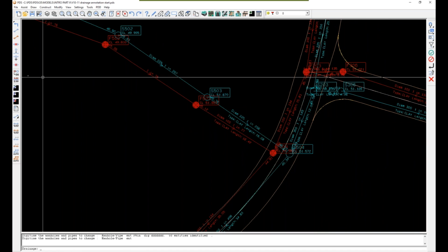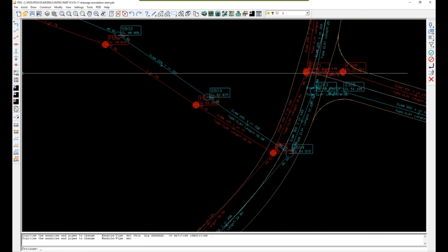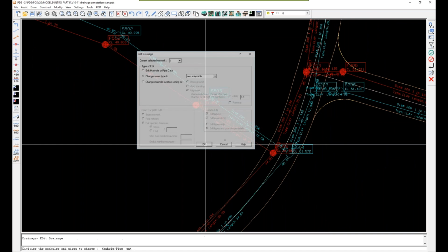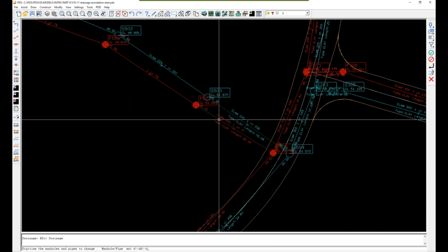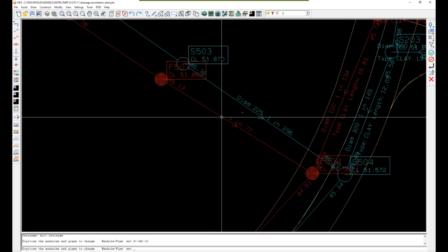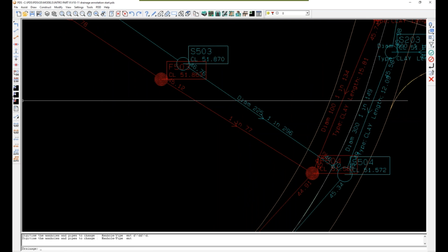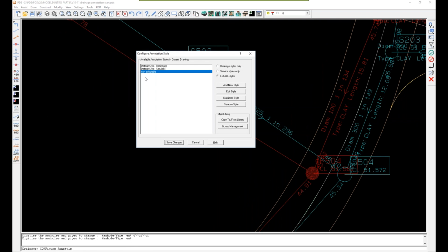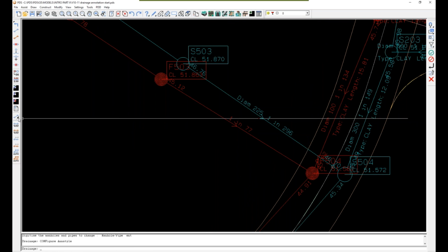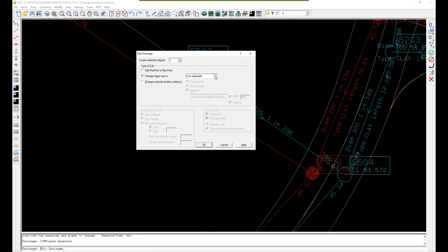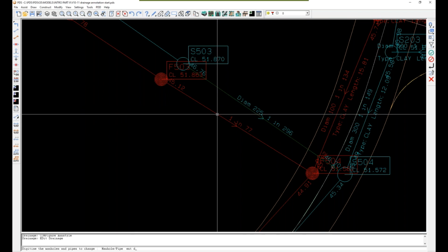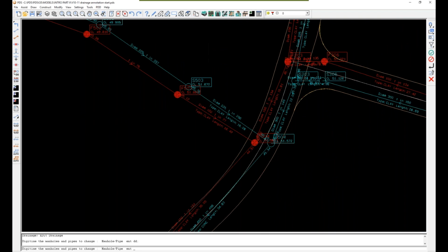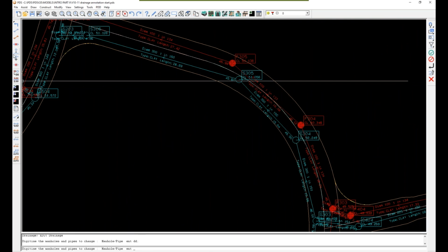If I do want to change them individually, I can do. So if I just pop back into Edit Drainage and say, you know what, those pipes might also be the non-adoptable style. And you can change the style of the pipes at any time. If I get that wrong and I say, oh no, actually those were meant to be back to the sort of adoptable, my default style there, okay, I can do that just by going into Edit Drainage and saying, actually, you know what, default style, I'll just pop them back to how they were. So you can go and change these styles at any time.